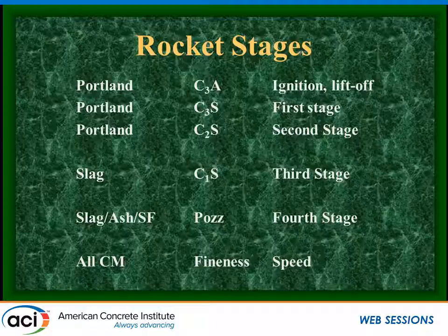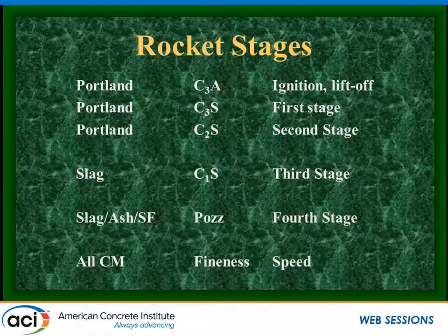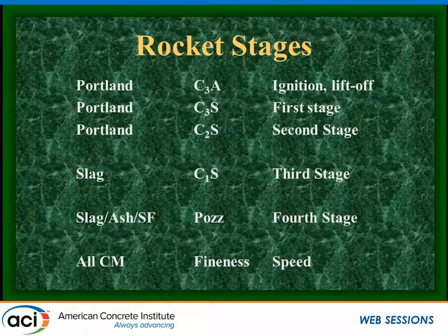Then, if we have slag in the mix, that's reacting, and that's going to carry us in and give us additional strengths from 21, 28 on up to 56 days. And then the last thing that happens is our pozzolanic reaction, where those aluminosilicates are reacting with our free lime and giving us even more calcium silicate hydrate that carries us on out further.